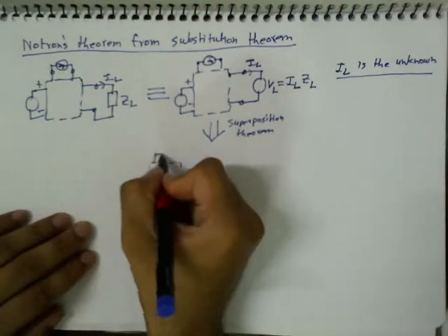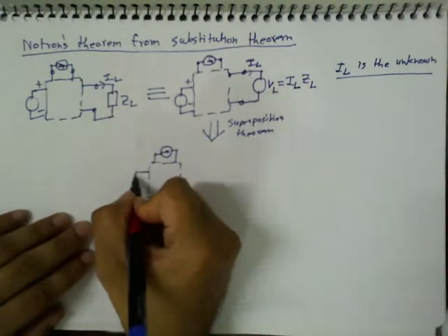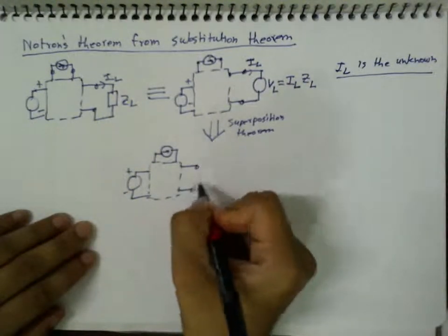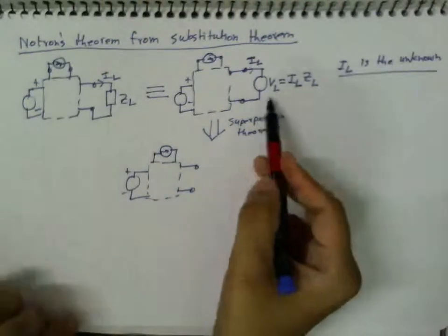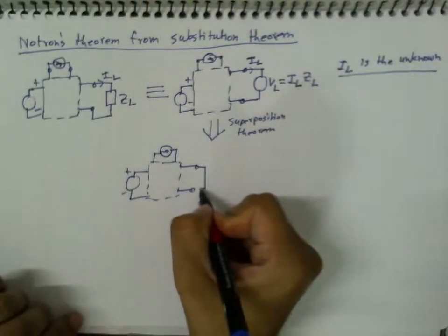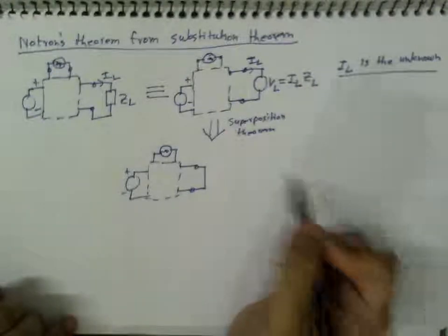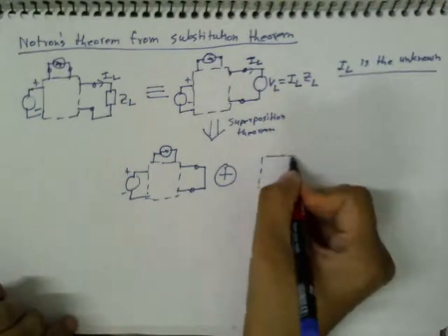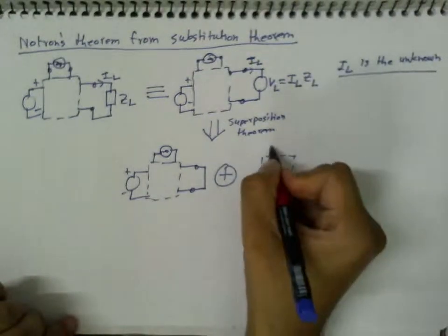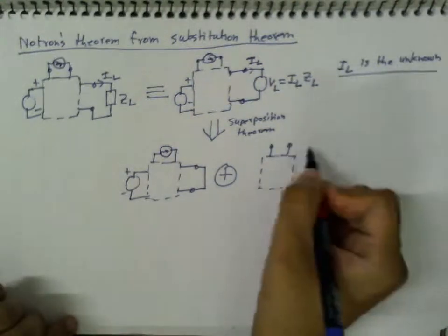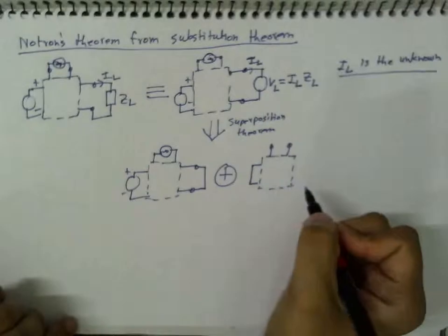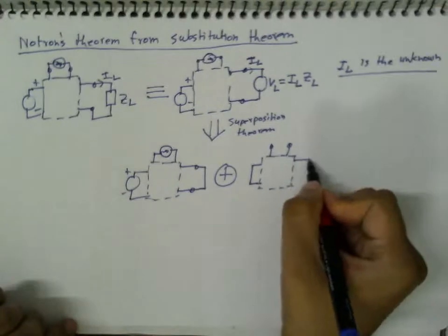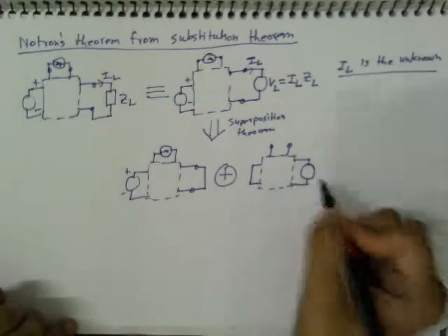with the internal ones, but the external one will be deactivated. But this is a voltage source, so by deactivating we mean to short circuit it. Okay, this circuit plus I draw the shunt network. Now I deactivate the internal current source by making it open and deactivate the voltage source by making it short, which is internal. But now I need this one to be present.